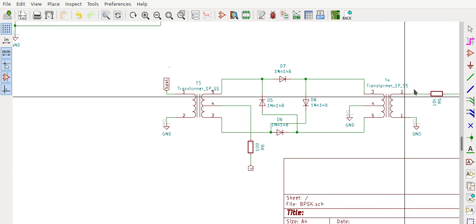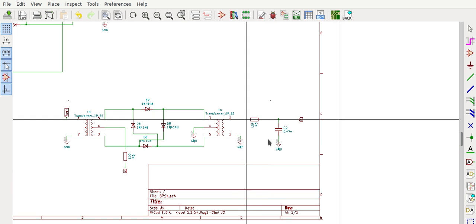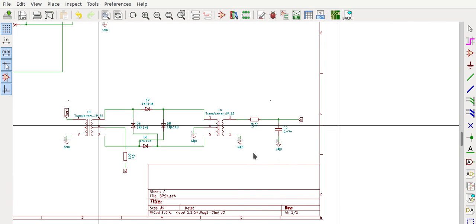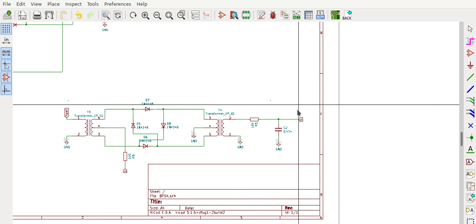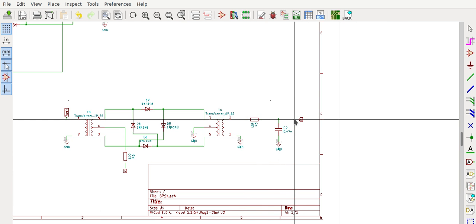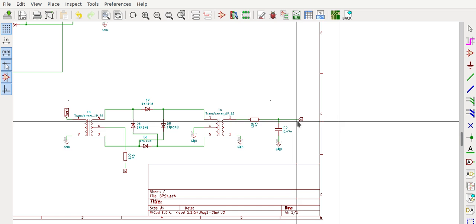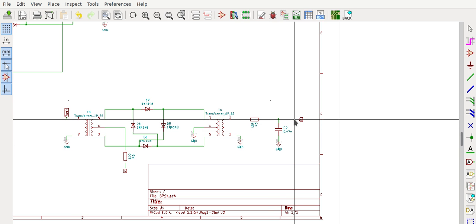out here we should have the demodulated signal, which I am then filtering using an RC low pass filter, because this will be baseband information that we will be getting here, and it can have a frequency spread from 0 Hz to say 10 kilohertz, and therefore we cannot use a very sharp band pass filter or band reject filter.